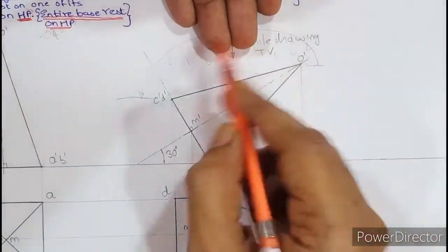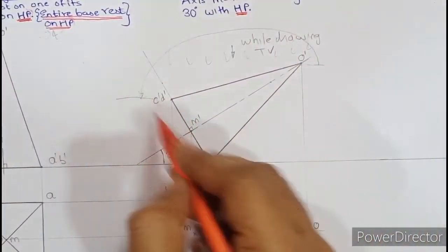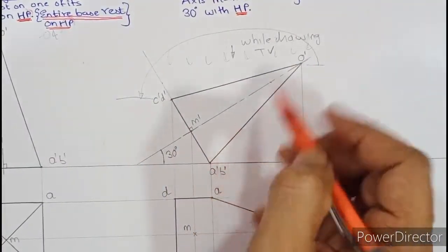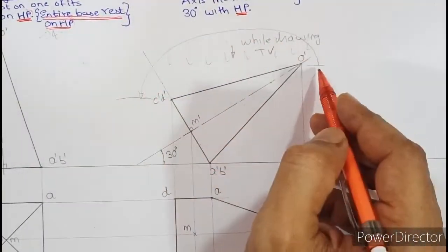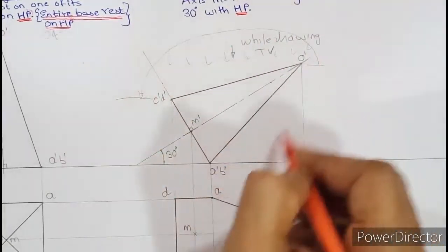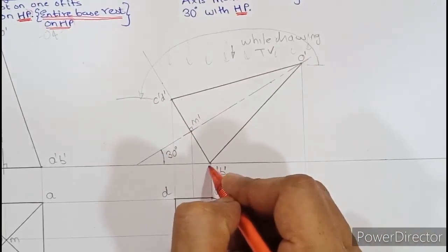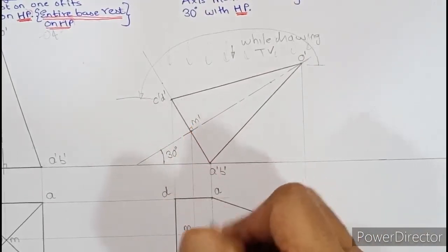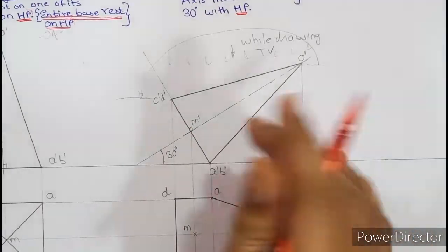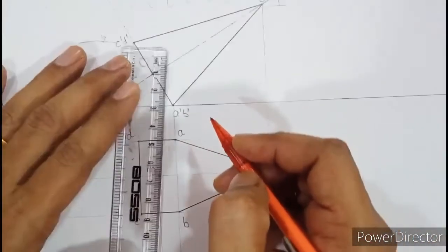CD is the maximum extent. You cannot see what is beyond that. You might have studied that half the part is light and half is dark. So O to CD will be in the light portion and the remaining will be in dark. Because the bottom half is in dark, you cannot see AB because AB is beyond 180. Therefore AB has to be hidden. I think this method is also a good method. So here AB has to be shown hidden.